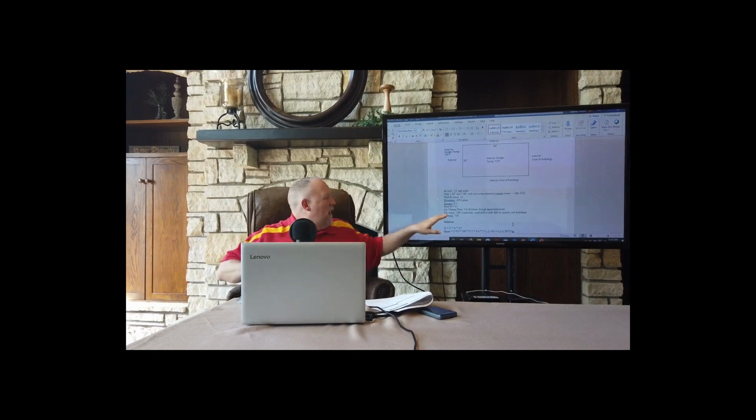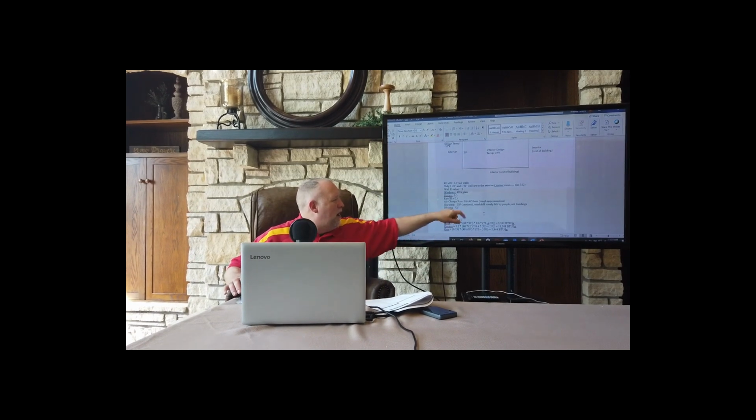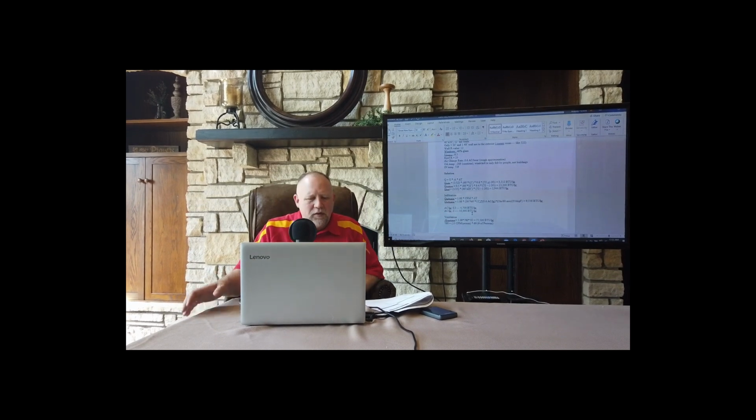I gave you the air infiltration rate of 0.6 air changes per hour, which we said is a rough approximation. Now, notice the outside air temperature is minus 20. Like I said, I'm being cautious. That's not wind chill, though. Wind chill is only felt by people. It is not felt by buildings. Wind chill is just that the faster the wind blows, the faster your body loses energy, and that's why it feels colder. But we're going to use real temperatures. Inside temperature is 72. Let's go through the solution.